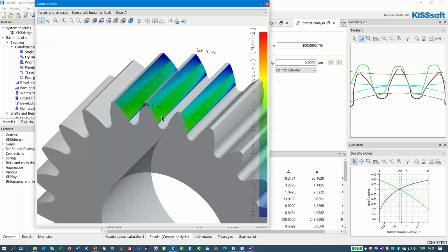This means if you have a symmetrical design of the gear body, then sometimes you have the draft angles working against each other, and sometimes they help each other. And I don't like this. So if you have draft angles applied, try to make the design such that after assembling the gear set, the two draft angles compensate each other. That's the best solution. Otherwise, you have an uneven load distribution from the left side to the right side.